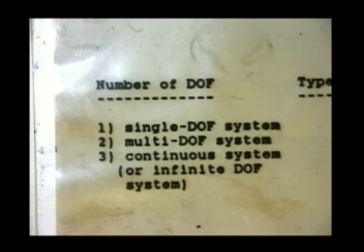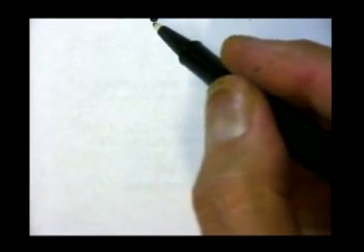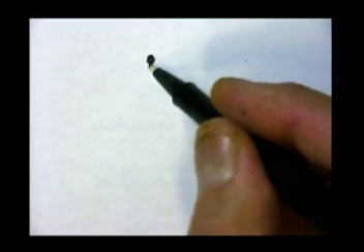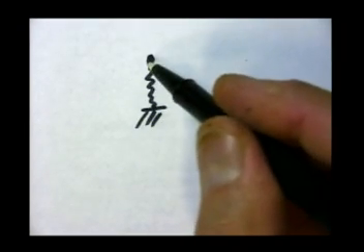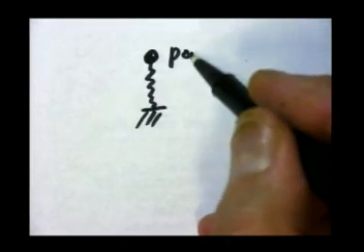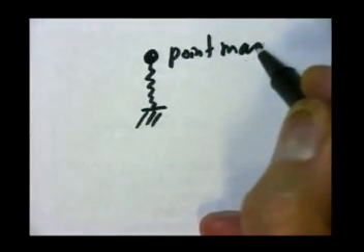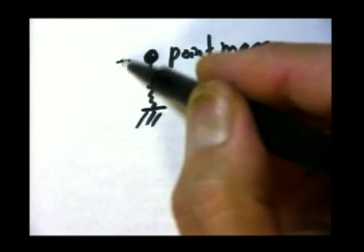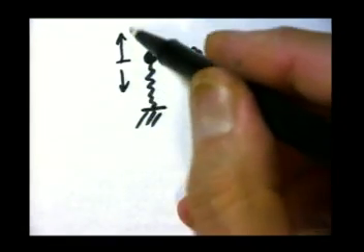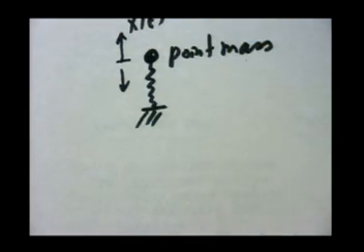So for example, let me bring an example. A 1 degree of freedom system could be like a concentrated mass, and say this is some spring, and it vibrates. This is a concentrated point mass. What I need is to know this coordinate x, and this vibrates like here and there. If I know x of t, then I know what happens with this system at any time t.